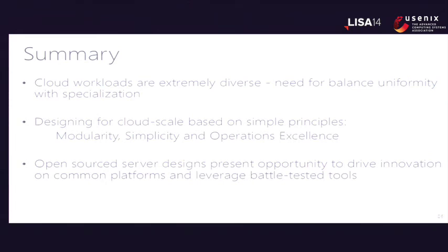Is the management board hot swappable? The management board on the backplane, is that hot pluggable? Can you replace it without bringing down the whole system? Right. It's hot pluggable in the sense that, suppose there was some issue and you unplugged it, then the system would default to a safe state, like the fans would go to max speed and whatnot. Then when you plug the new one in, it will detect that the new one is there, and it will go back to the normal state. So you don't have to shut everything off to be able to change it. That's what your question is.